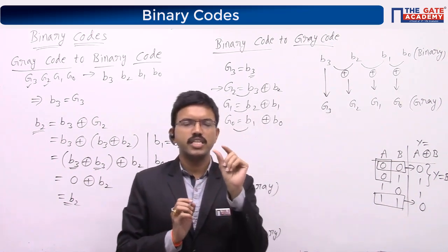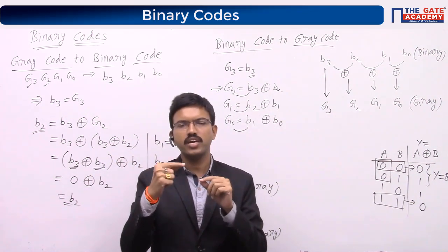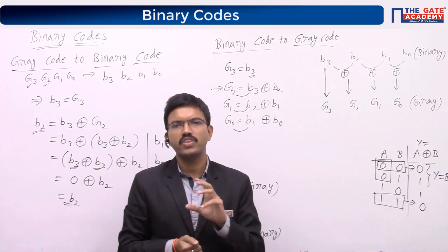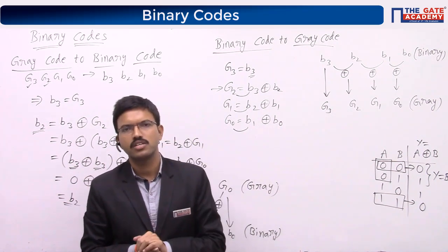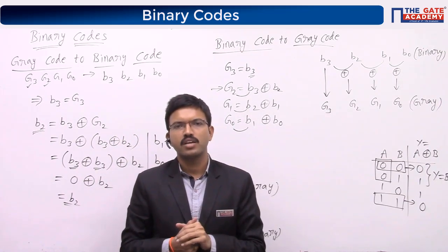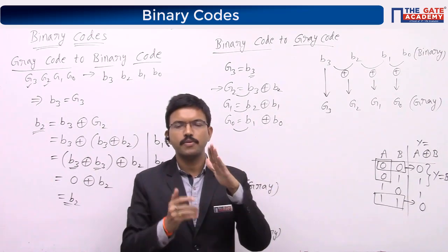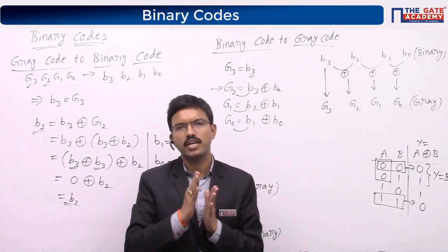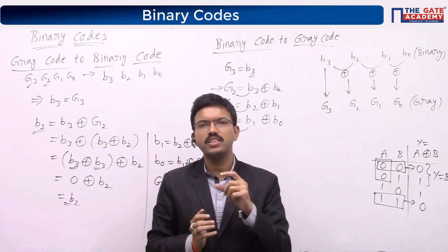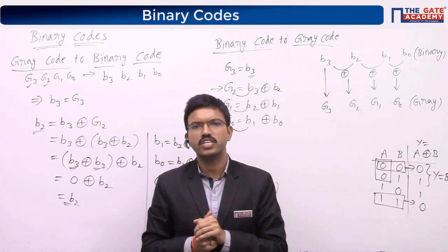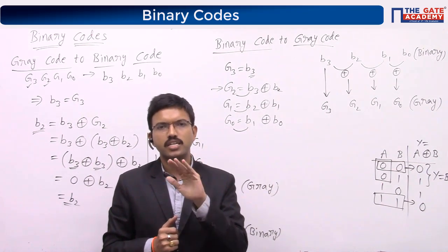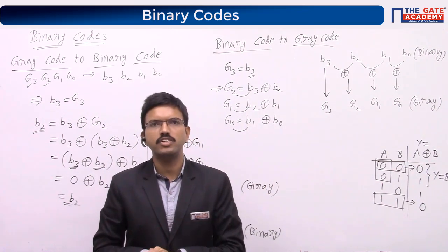Since it is a continuous rotational process, you may get ambiguity with binary code, because the position of the shaft must be represented exactly. Suppose you have 12 segments or 8 segments; if you represent each segment with binary code, there will be ambiguity in knowing the position of the shaft. With gray code, for any two successive segments, only one bit position will change.